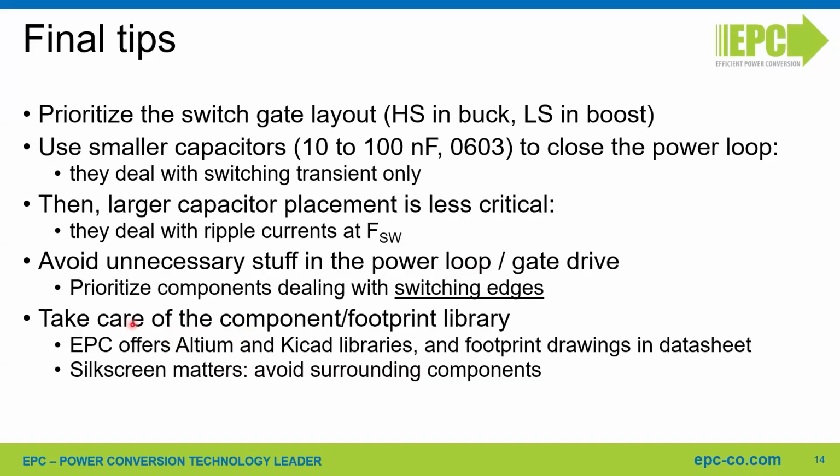And then it's important to start with the right footprints for our components. As EPC, we provide Altium and KiCad libraries, and we have reference footprint drawings in the datasheet. And also the silk screen is important. We advise not to surround the component with a plain box of silk screen, because it causes worse removal of the flux when you clean the boards, or can trap the flux under the device.